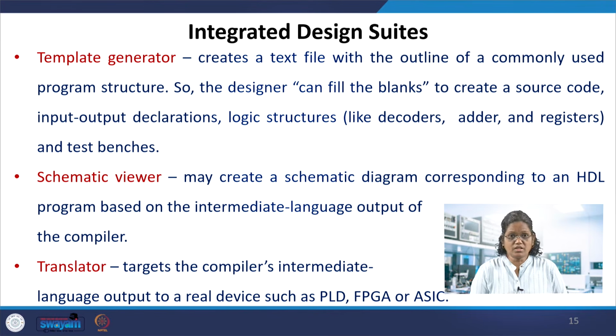So the translator, which is the next one, after the template generator and schematic viewer, targets the compiler's intermediate language output to a particular device, which is the FPGA. So it gets translated into the diagram given by the output of the compiler, and takes the FPGA resources. In the logic blocks we have LUTs, flip-flops and muxes. So what things need to be used for your design is decided by this translator.